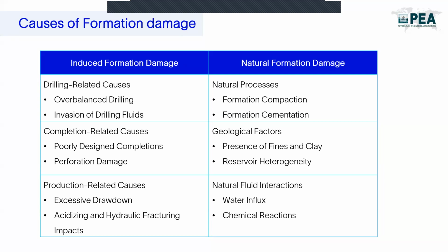I'm not talking about the fines migration that will be covered in the other part, natural formation damage, but it could also be a result of high drawdown applied to our well, which will trigger the fines to migrate throughout the reservoir, blocking the pore throats.